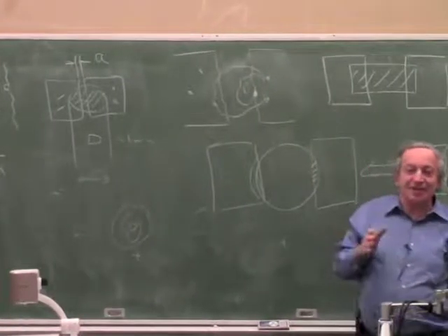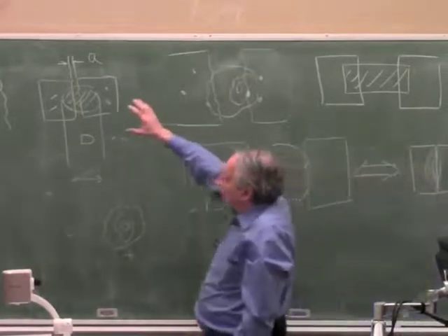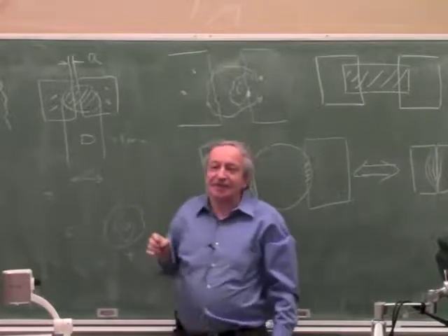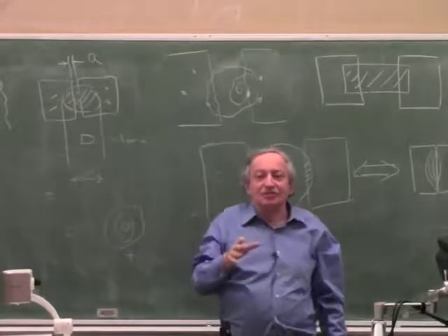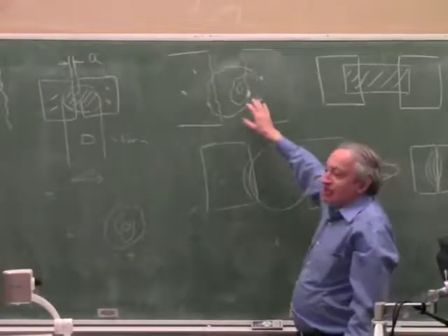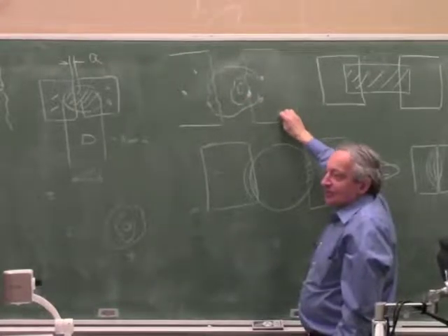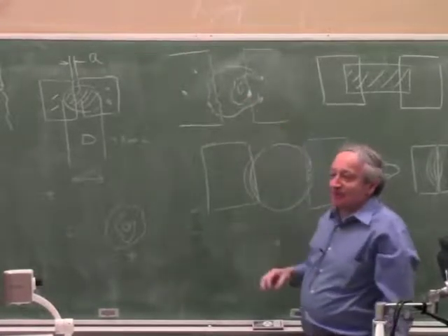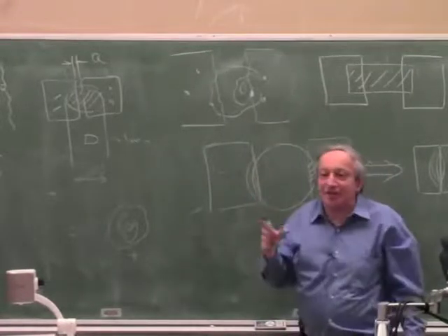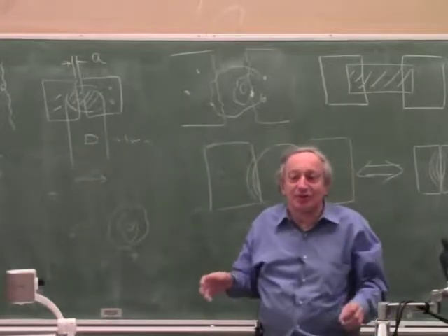So the practical reason why it's better to make a big spot is two reasons. A, averaging, and secondly, a reason you didn't think of, and this I didn't expect you to think of, because silicon will saturate. If you put all the light in one spot, the spot will saturate, so actually it will not work at all. You have to be very careful not to saturate the silicon, otherwise it stops being linear, and my theory of linear superposition stops working.